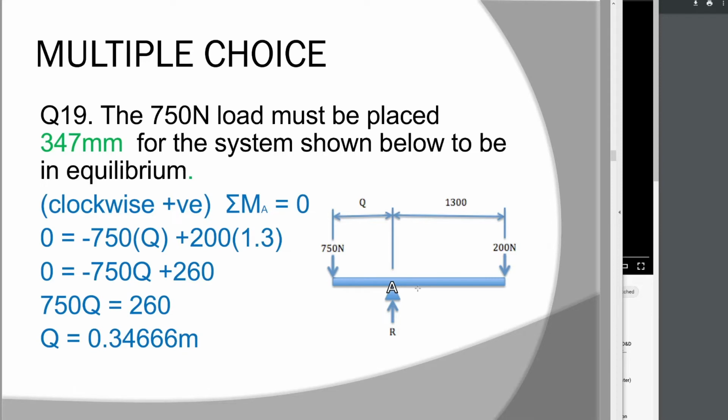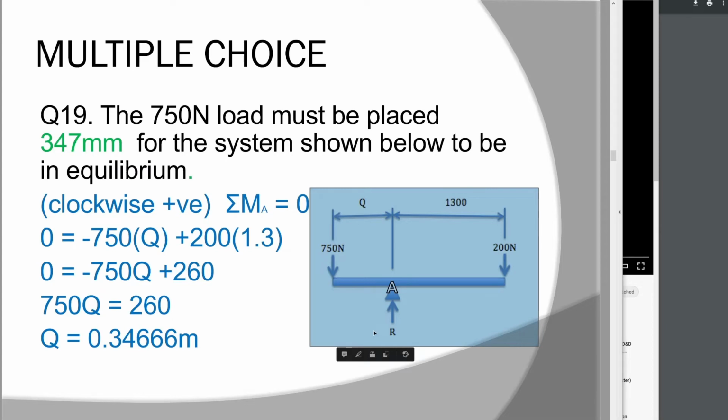Okay, so here we have a nice easy first order lever, and we're going to find the moment forces. It's a pretty easy moment question as far as moment questions go. The idea is that although fat kids always win at seesaw, they don't if they sit closer to the fulcrum. So what we're going to find out is that although this 75 kilogram person under Earth gravity, versus say their 20 kilo child, if they want to balance out, they could slide forward. How close would they be? Well, if the kid is sitting 1.3 meters away, they might sit only 0.3 meters away. Okay, so most people are okay with that.